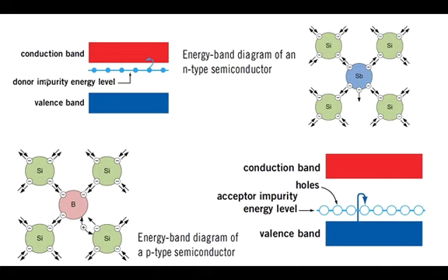So when you dope, if you introduce an extra atom with 5 valence electrons into the system, every extra atom that you introduce in the lattice introduces one extra electron, and these are all localized electrons. So essentially you introduce extra energy levels, and these energy levels contain all these extra electrons. Remember, even if it is drawn as a straight line like this, it is essentially discrete energy levels at the same energy, and they are all localized states.